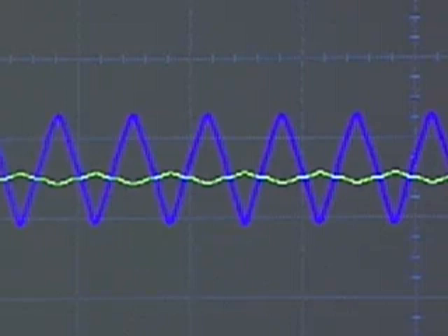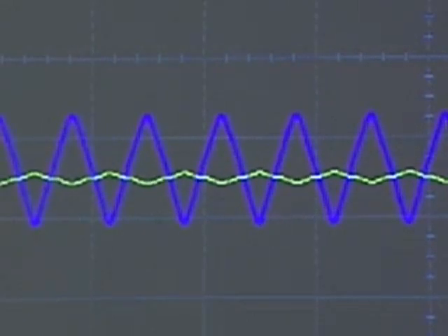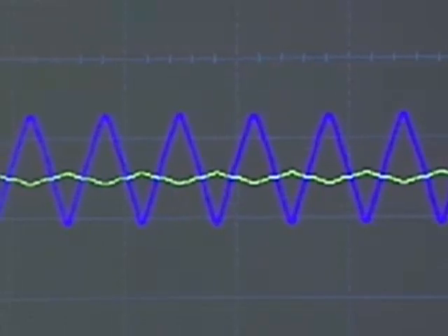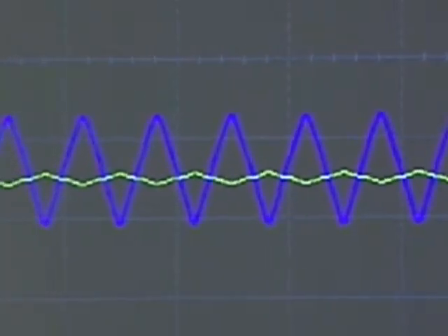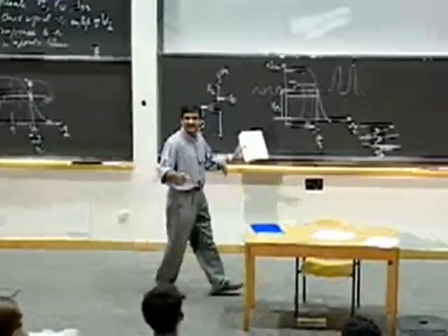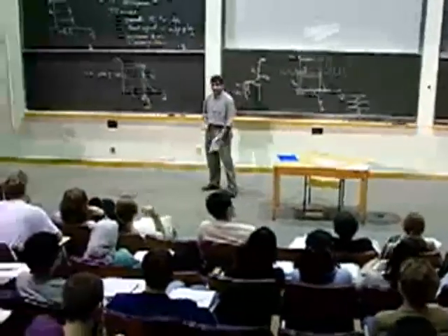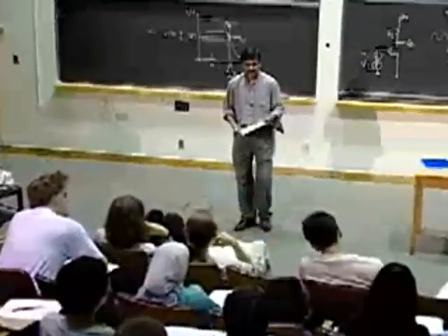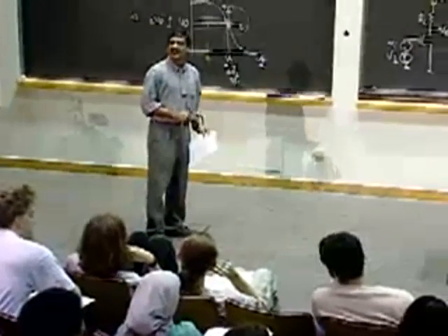What I can also do is change the bias, and we'll see this at the end of the lecture, in the last 10 minutes. How do you select a bias point? By changing your bias point, you can change the properties of your amplifier. To give you a preview of upcoming attractions, what do you think should happen if I change the bias point? I haven't shown you the math yet, so intuitively, if I increase the bias, what do you think is going to happen? Yes? Higher bias will be more amplification. Good insight. Higher bias will be more amplification.